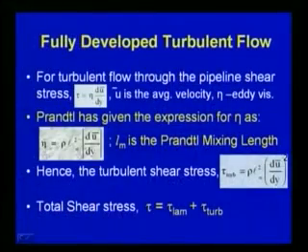So, generally, as far as turbulent flow is concerned, for various flow parameters we consider a mean value and then the fluctuating portions. If we consider turbulent flow through a pipeline, the pipe systems, and as far as shear stress is concerned, we can represent the shear stress tau is equal to eta du bar by dy, where u bar is the average velocity and eta is the eddy viscosity. We have discussed these details earlier.